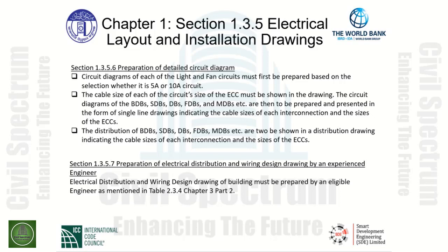The distribution of BDBs, SDBs, DBs, FDBs, MDBs, etc. are to be shown in a distribution drawing indicating the cable sizes of each interconnection and the sizes of ECCs.